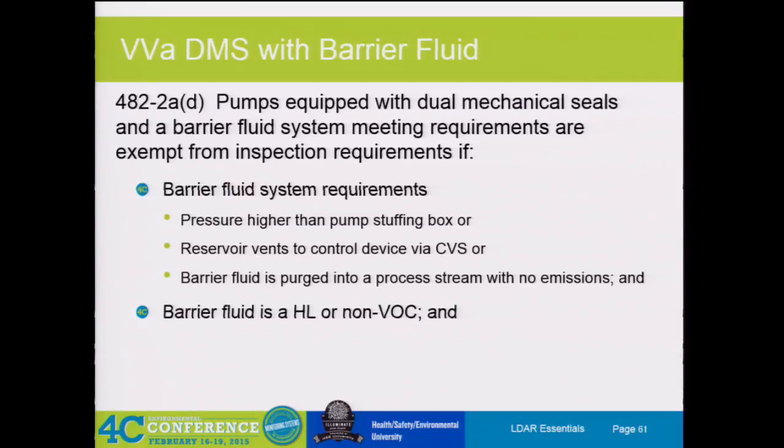So pumps equipped with dual mechanical seals and barrier fluid systems are exempt from the inspection requirements. I talked about that earlier. As long as you have some kind of alarm that tells you that this thing is going off. So you can either have an operator doing rounds, checking a pressure system to see that your barrier fluid space has gone up in pressure.